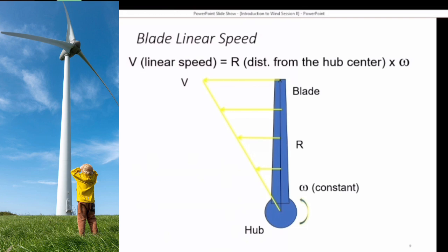The more you increase the weight of the blade, the more stable the system becomes. Even when disturbed by the variation or intermittence of wind, it will just keep rotating. Because even by stopping the wind speed, this will rotate for at least a certain minute. When you give it a speed, of course, it will never suddenly stop.